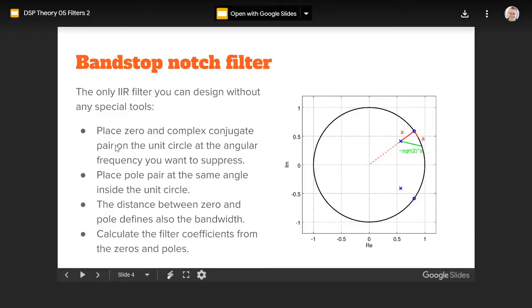This is pi radians. That will be somewhere in here. Noise, meaning that on the spectrum there is a peak here. For example, 100 hertz. You have a rectifier, full wave rectifier. It gives you 100 hertz humming, not 50 hertz, but 100 hertz.